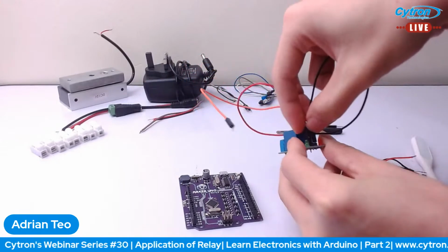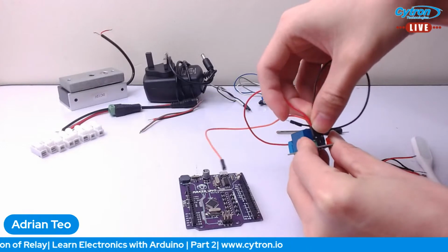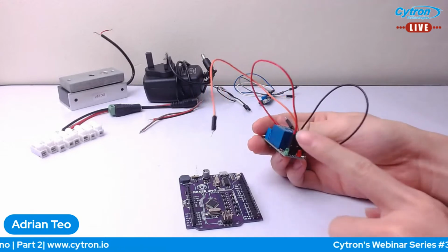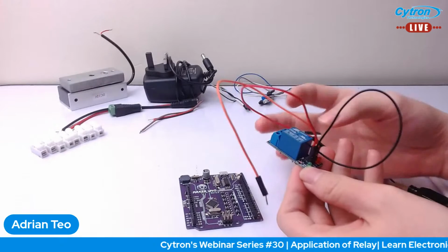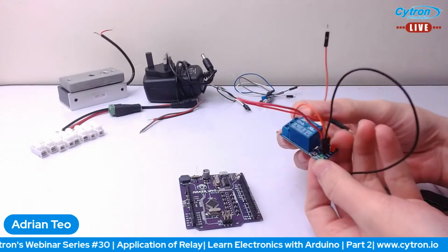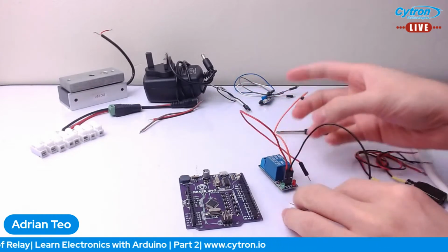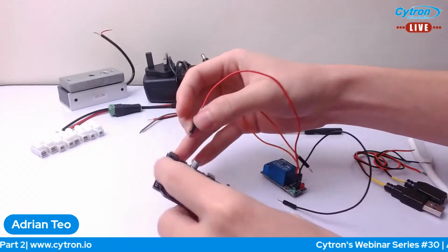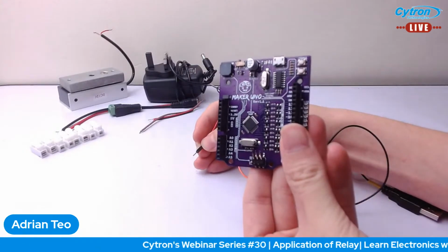So connect the 3 wires to the 3 pins on the other side of the relay, like that. The ground and the VCC are to power up the whole module with the relay, and the orange wire is to control the relay, whether it's supposed to be in on state or off state, depending on the program, high or low. So VCC, I'm going to go ahead and connect it to 5 volt. Okay, 5 volt on the left.